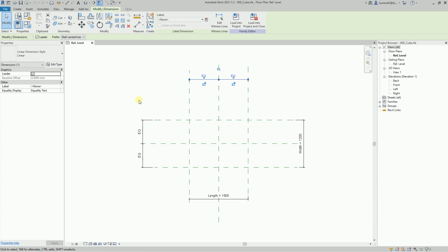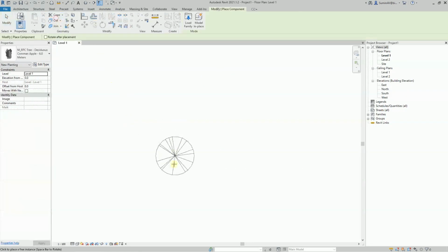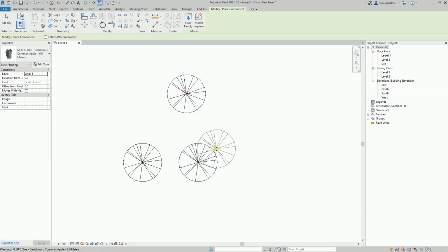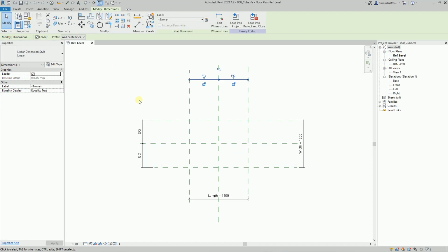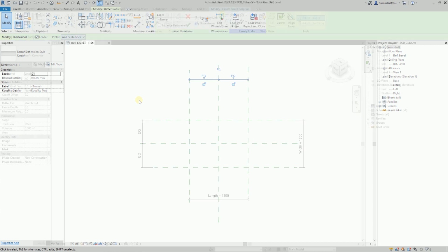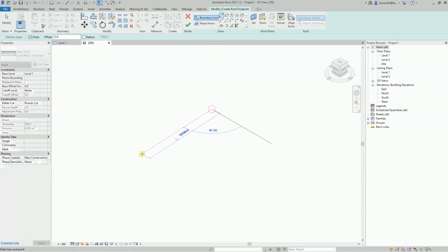The second technique is point-based modeling. We set a point in the model space, and the geometry is formed at this point. We use this technique to create columns, pieces of furniture, or equipment. In the same way, we can create utility system fittings or fixtures. Last but not least, the third technique is sketch-based modeling. A 2-dimensional sketch is drawn to be transformed by the software into a 3-dimensional geometry.